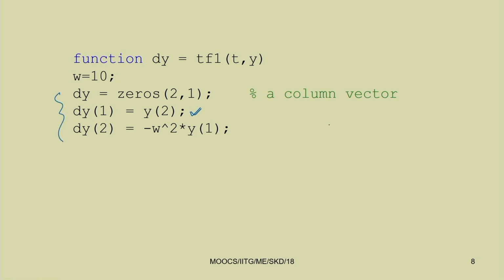Let you write the Duffing equation in this form, that is x double dot plus omega n square x plus alpha x cube plus 2 zeta or 2 mu x dot will be equal to f sin omega t or f cos omega t, let us put, you can put f sin or f cos omega t.